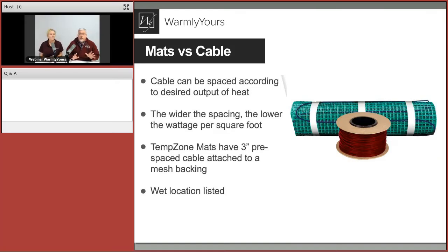Yeah, this is a very popular slide. We got lots of questions about this slide. But if you embed the product, you then have a better chance of getting the manufacturer to certify that. Interestingly enough, many of these manufacturers will warrant wood and laminate under hydronic radiant heating, which is using pipes with warm water. They'll actually warrant under hydronic, but they're less familiar with electric.